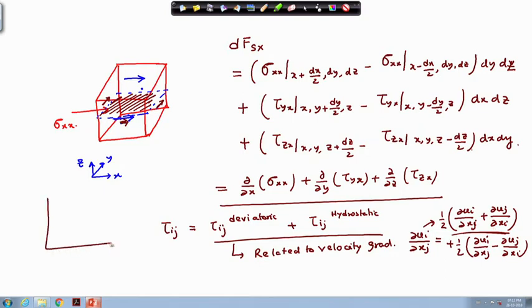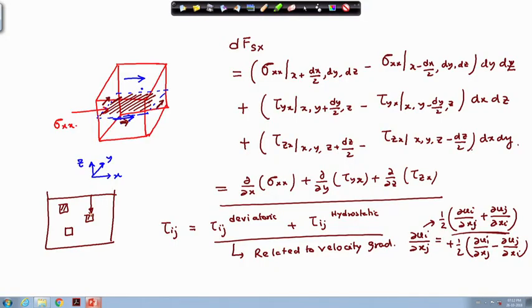And a very good example is if you take 2 or 3 identical control volumes within a static layer of fluid. Of course, the body force on each of them is going to be the same, but however, since they are at different depth and the pressure distribution here is purely hydrostatic, they will be subject to different levels of normal stresses in this particular direction, which is not related to any deformation, because since there is no flow, there is no deformation.